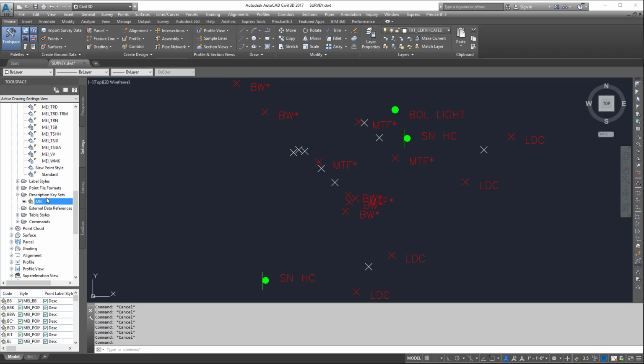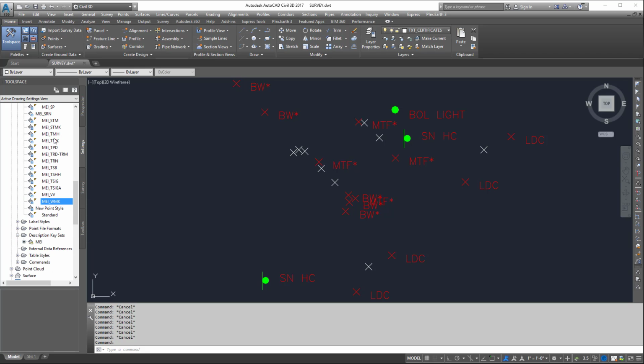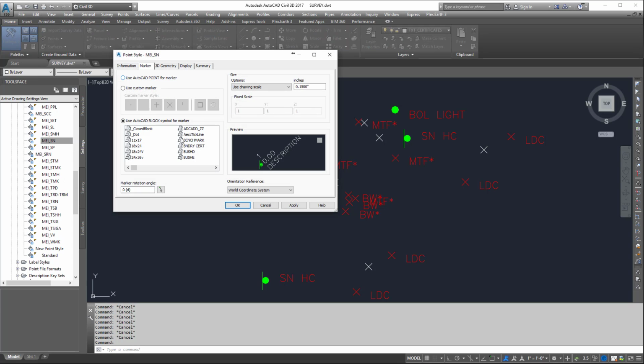And all these are, so these blocks or the sign here, we'll go to it over here. So all these things are just blocks. So all your blocks that you currently have or have used before aren't for naught. You can still attach them and use them. Note, sometimes the blocks you used before are either too big or too small. So you probably will have to adjust the drawing scale on them as well. Especially if you forgot to change your units.